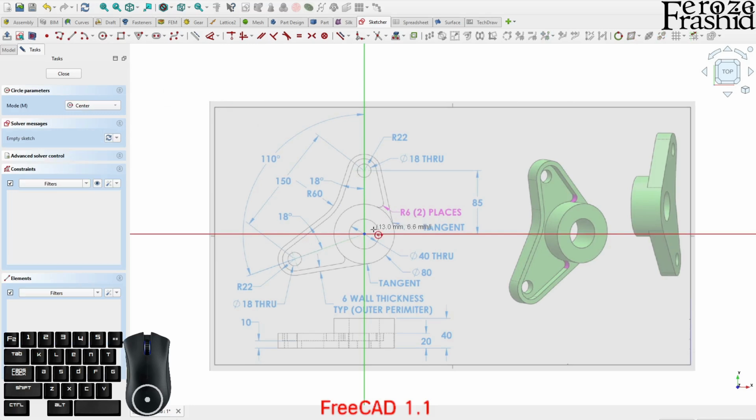What I want to do is draw a, well, I was gonna draw a circle, but I think I'll draw an arc instead. So it would be a center actually from here to there. I want to draw that arc. And then I want to take this polyline. Polyline is a combination between line and arcs. I'll use that.